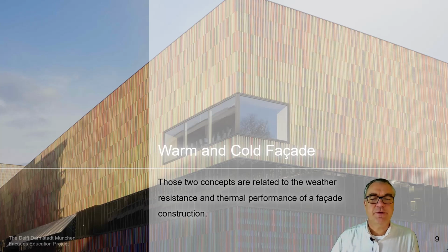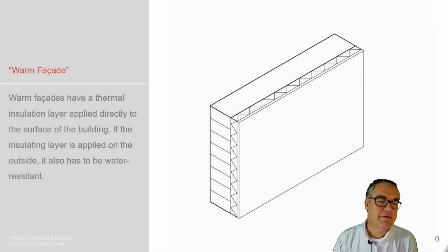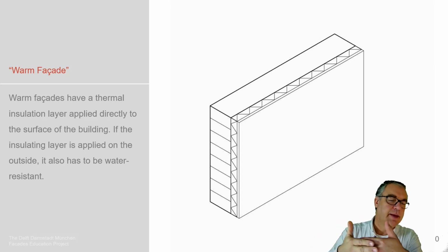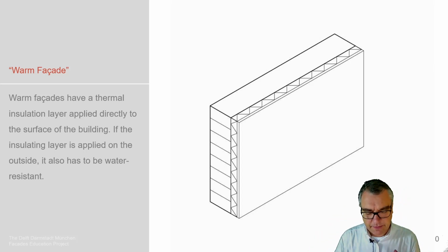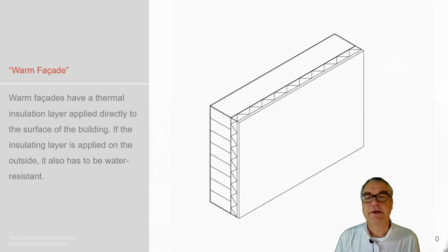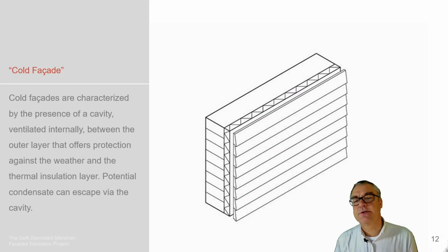We have two ways of doing these solid walls, warm and cold facade, as we define them. The system warm facade works in the way that we have an inner solid structure. Then there's an insulation layer, which serves the question of insulation of this main structure, which is then covered with, for example, in this sample, a plaster. This is how it may look like. You see it's an inner solid structure. Obviously, there's some insulation placed, and then the whole thing is plastered to wrap the system.